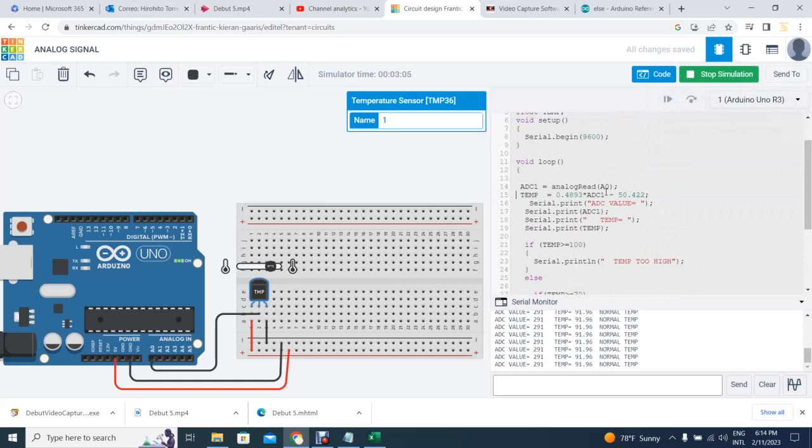Thermistors are harder than that. A thermistor might end up having many regions which are linear, but many regions together. You know what I'm saying? You might have three linear curves to describe the full range of the thermistor. So you want to be careful at what range you are, to use the proper equation, which is linear.